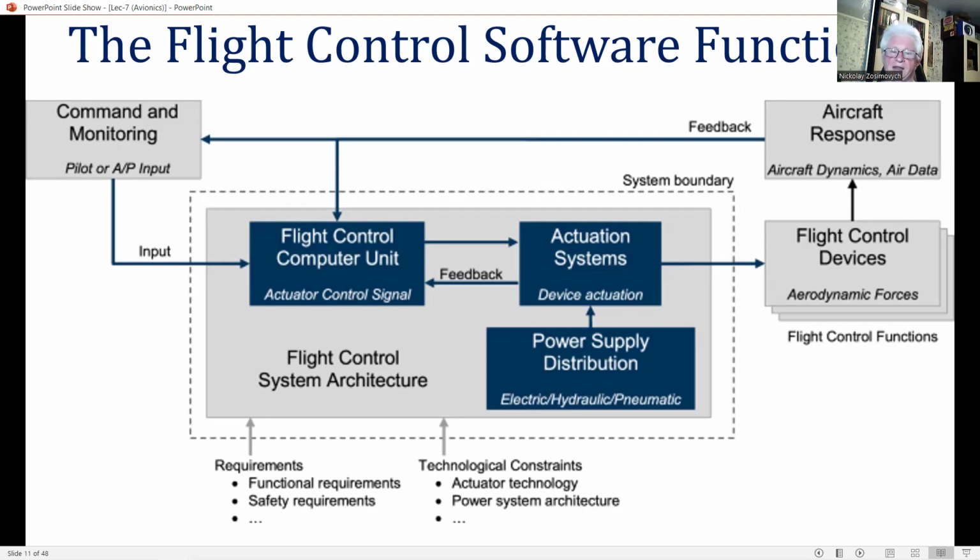Built-in test software for in-flight monitoring accounts for a smaller percentage of the total software, in either case around about 10%. However, during the pre-flight checking stage on the ground, the proportion of the operating software taken up by built-in tests is much higher and can be as high as 40%.